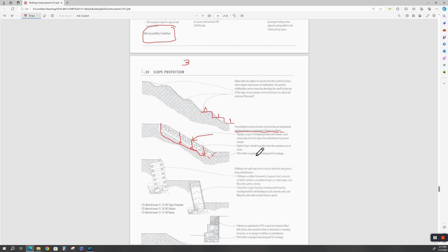The depth and layers should be much greater than the maximum size of the stone. Well, that is very true. But that's a riprap, and it's usually broken or random size. I've seen them use the heavy wash stones where they want it to look cool. A lot of times you just have broken up concrete.